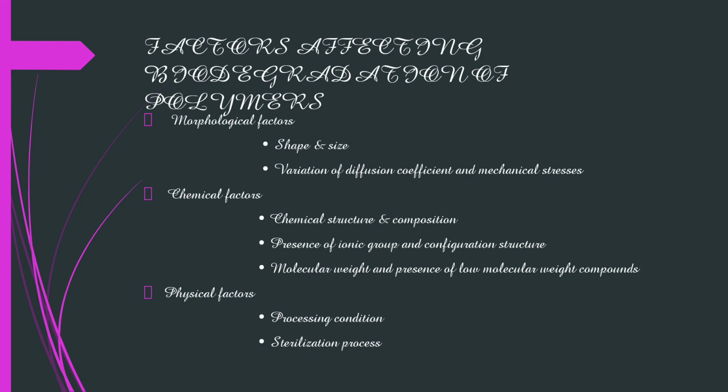Factors affecting biodegradation of polymers. Mechanical factors: shape and size, variation of diffusion coefficient and mechanical stress. Chemical factors: chemical structure and composition, presence of ionic group and configuration structure, molecular weight and presence of low molecular weight compound. Physical factors: processing condition, sterilization process.